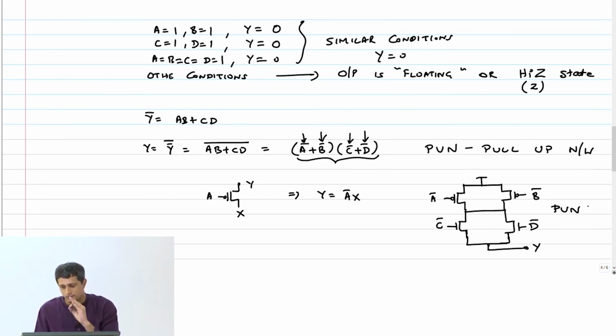So the first useful lesson here is when two outputs are floating in a complementary manner, right? When the output is 0 in the pull down network, it goes to 0, otherwise it floats. In exactly those conditions, that pull up network is going to pull it up to VDD. So therefore, I can tie these two outputs, do a wired OR connection on these two things and get a proper output, right? So to implement this function, Y equal to AB plus CD whole bar.